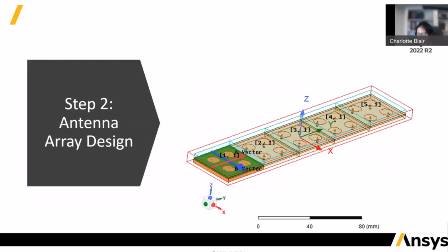Again, yes, I can automate it. And we do have automation tools. We do have a PyAEDT script that we can write to create it. But we already have that within Ansys. I can create an element, a 3D component element, an HFSS submodel of this unit cell. And then I have a finite array wizard that says, oh, I want this to be replicated a number of times in a row, and I want this many columns. So I can automatically create it.